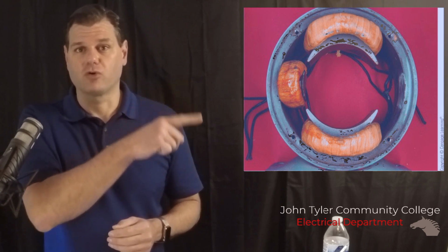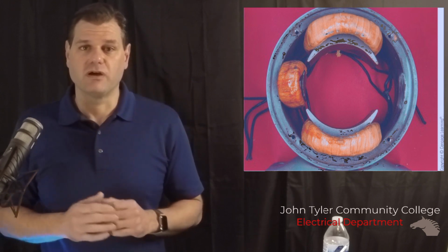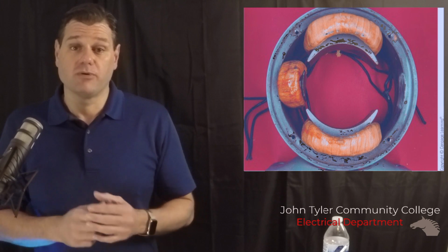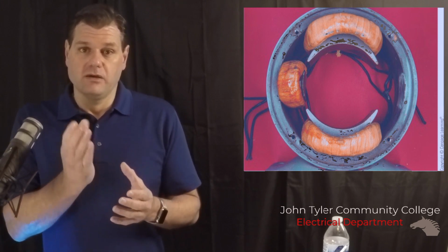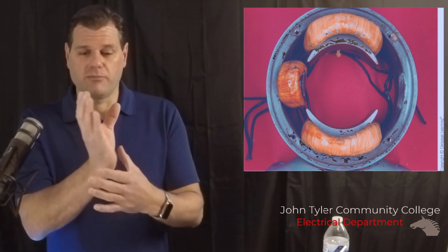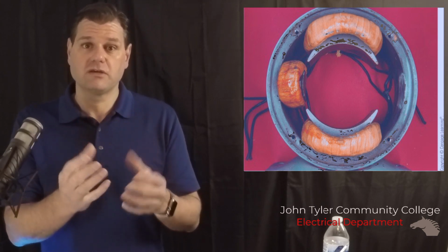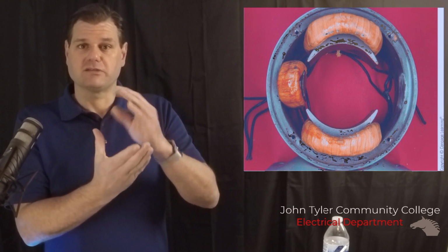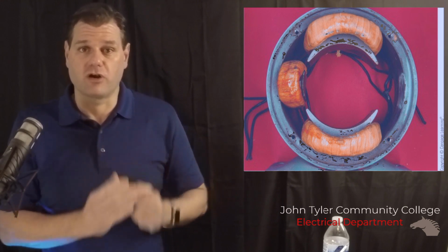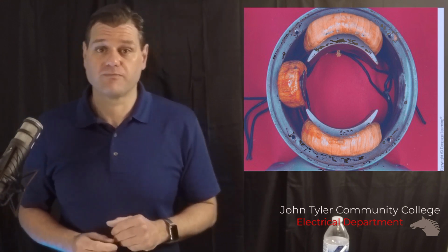You can see here that little horseshoe shape at the top, and that is the pole piece. The part you see at the bottom wrapped around is going to be your field windings, and the pole piece is sticking up because it's going to be riding really close to that armature. Not touching, but very, very close.